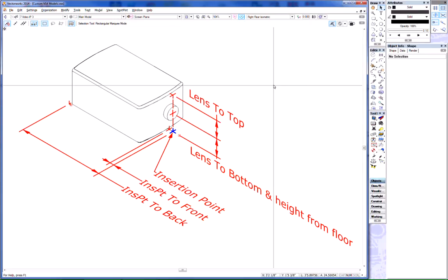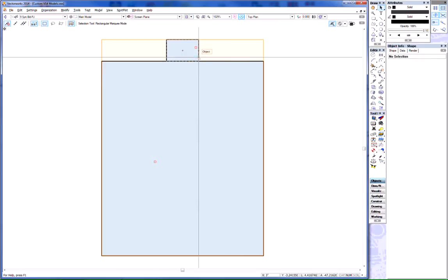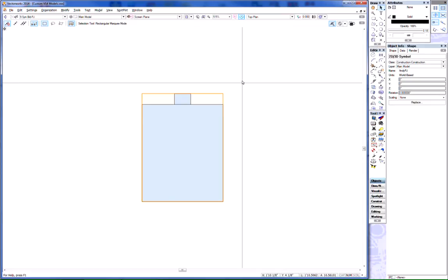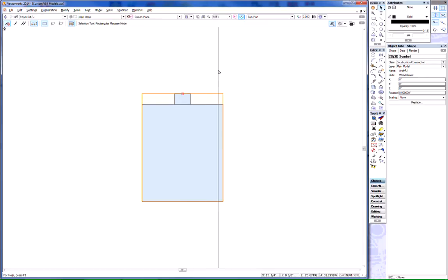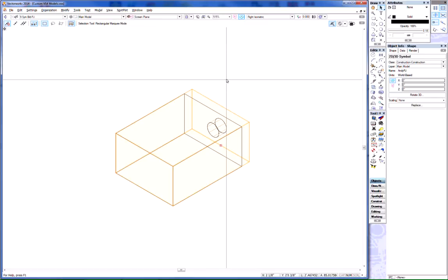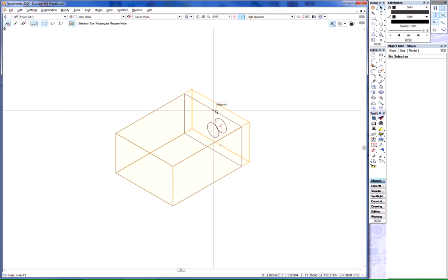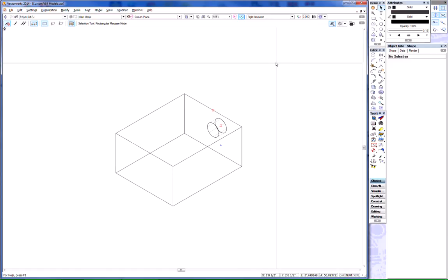Okay, so that's a quick look at the parameters that will go in. Let's go in and edit a symbol to make it work with VideoScreen. Here I've got a save view for projector construction, and you can see I've got a projector. It's already a symbol. We're looking at the 2D part. And one thing I want you to see is that zero orientation for a projector means it's pointed up screen. Let's go to a 3D view, and you can see our projector is simply a cylinder for our lens and an extruded rectangle for the body.